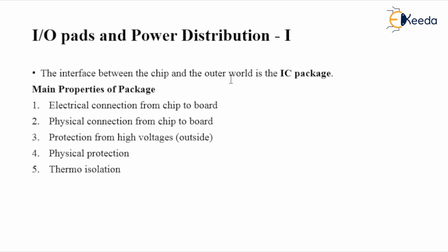The main properties of this package are electrical connection from chip to board, physical connection from chip to board, protection from high voltages which are applied externally, that is, from outside. Fourth one is physical protection, and the fifth one is thermal isolation.